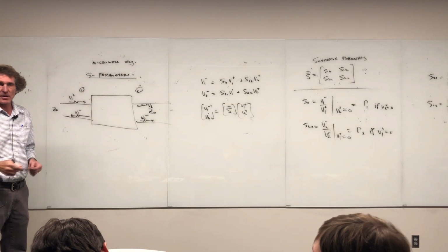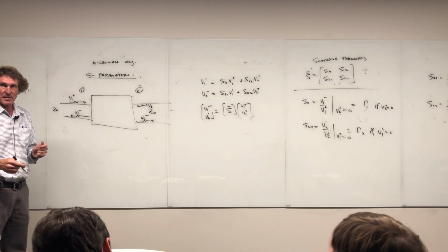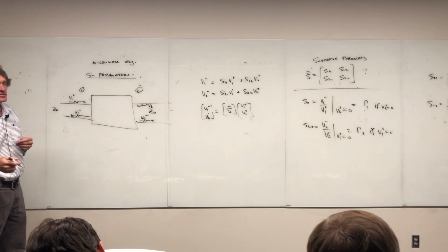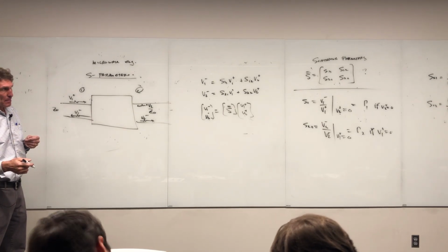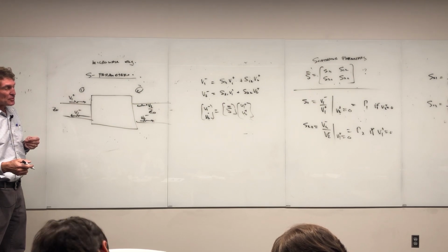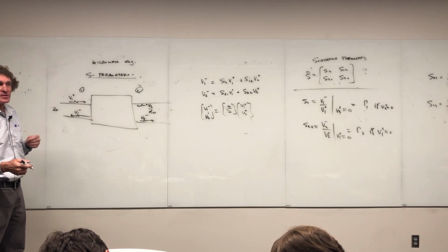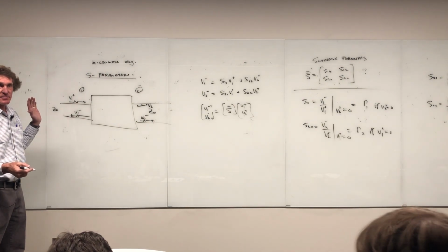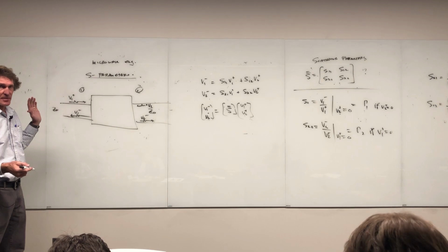This is the common terminology that they talk about. They talk about scattering parameters, forward gain, reverse gain. They almost never use the word reflection coefficient, but S11 generally is that. They'll talk about the forward gain or the forward transmission gain, something like that.